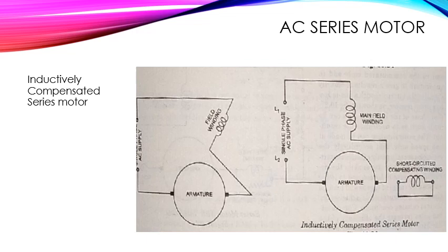The resistance and inductive reactance of the armature circuit of the inductively compensated motor will be increased over their values for the armature by a certain amount through the coupling of the compensating winding to the armature in accordance with the transformer action, and that's why the total resistance and reactance characteristics of the inductively compensated motor are practically the same as those for an equivalent conductively compensated motor.